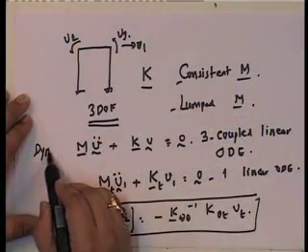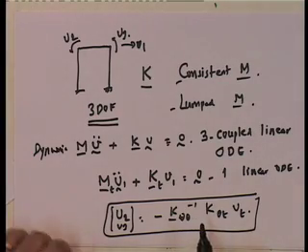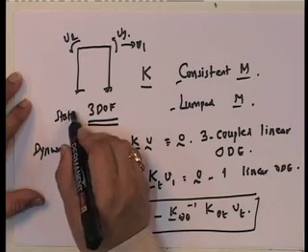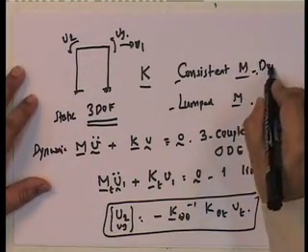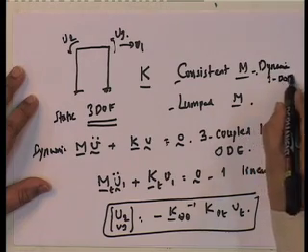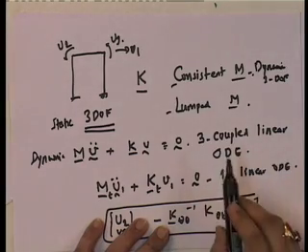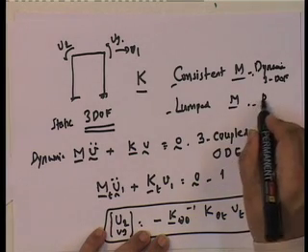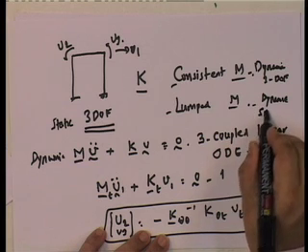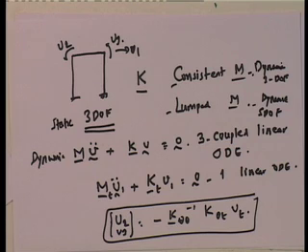So, in other words, you still have to get V1, V2, V3. The only thing that happens is that the dynamic problem is in terms of ODEs. So, static is still 3 degrees of freedom, and with consistent mass, dynamic is also 3 degrees of freedom, because you still have to solve 3 coupled linear ODEs. Use the lumped mass formulation, then dynamic is a single degree of freedom. You see the advantage? This is in essence why people tend to use the lumped mass formulation for framed structures, because it simplifies the problem.